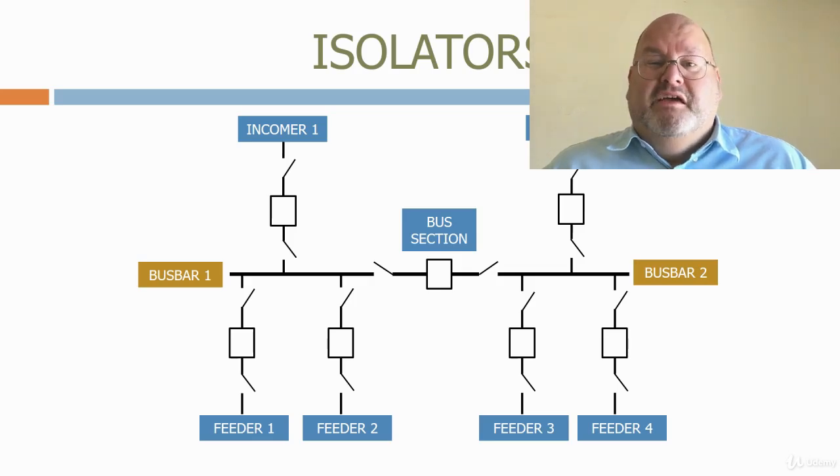You will find that either an isolator is used all the time or not at all, depending on its position in the circuit. Both of these scenarios can cause maintenance issues. When isolators are kept closed for months on end, the contacts tend to bond together due to current continuously passing across them, and when you come to operate the isolator, it can be difficult to physically move the arm.